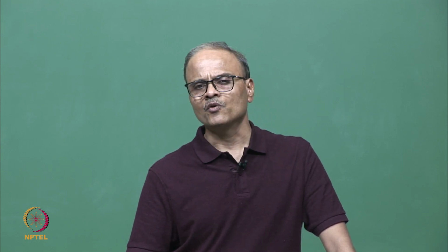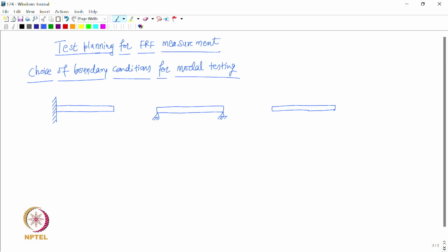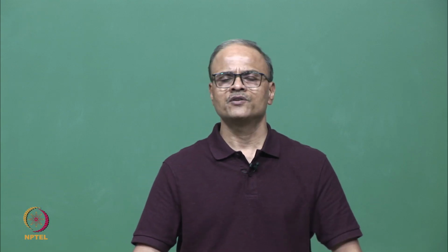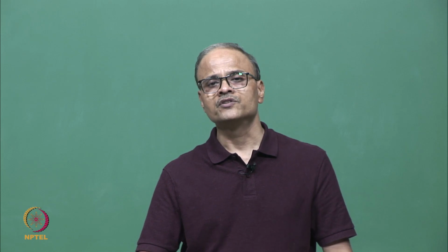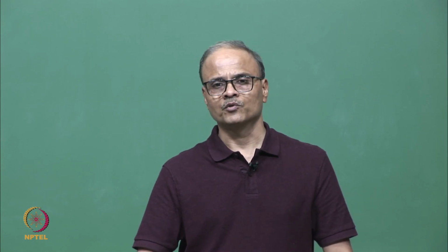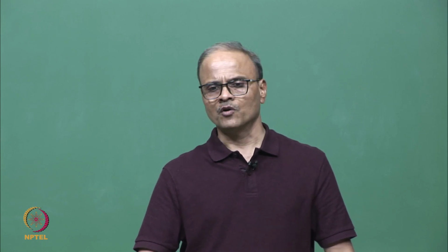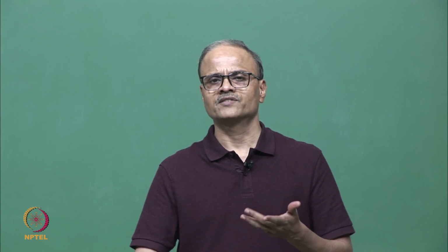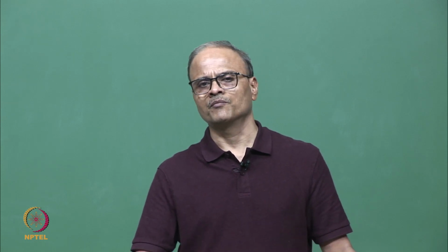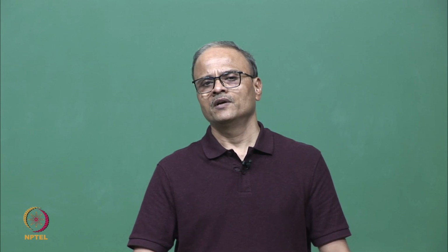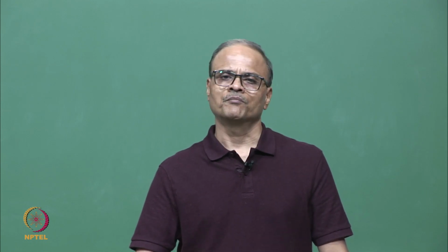Now what should be the boundary conditions for modal testing? The choice depends on the purpose for which the modal test results are supposed to be used. What is the objective of the modal testing, what results we are going to get from it, and what is going to be the application of that, basically determines the choice of boundary condition.